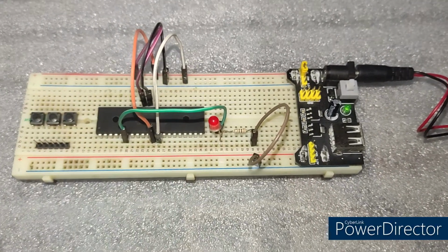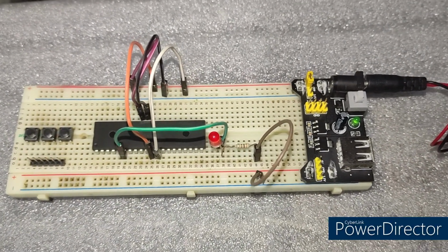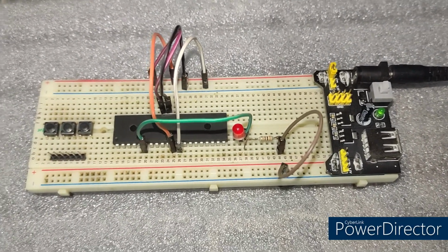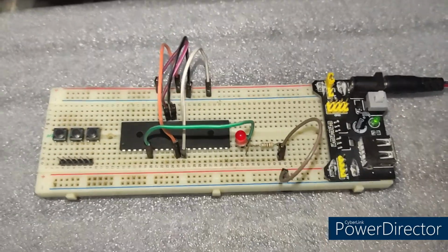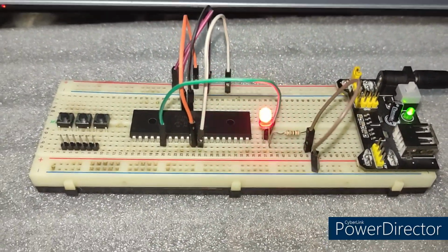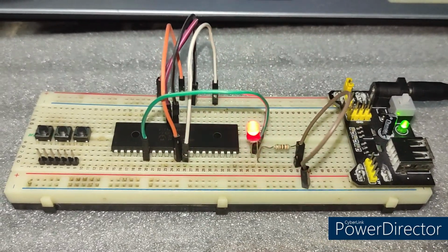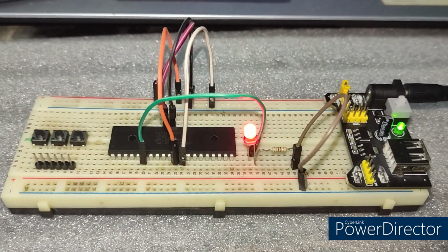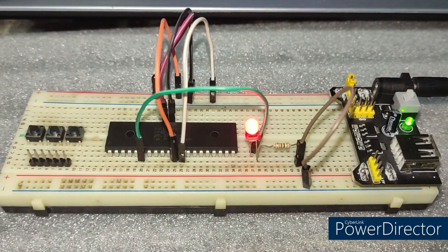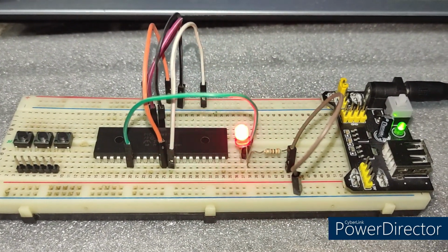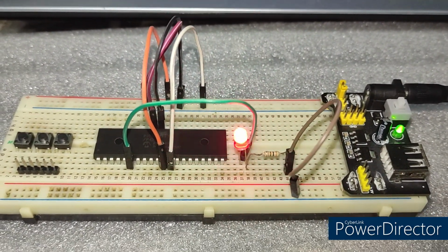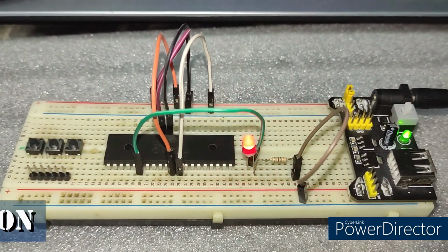So now to test our circuit, wherein we modified our code for the LED to adjust its brightness faster than the previous one, let's turn on our power module here. Okay, as you can see, our LED is adjusting its brightness faster, and it seems that it's blinking, but it's absolutely not. This happens because we increased our increment for the duty, which we adjusted to 60 from its previous value of 10.